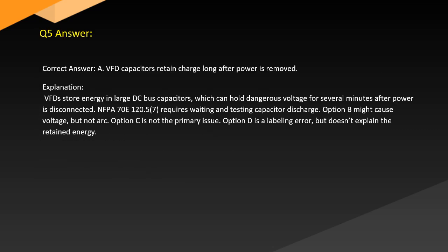Answer. Correct answer A. VFD capacitors retain charge long after power is removed. Explanation: VFDs store energy in large DC bus capacitors, which can hold dangerous voltage for several minutes after power is disconnected. NFPA 70E 120.5.7 requires waiting and testing capacitor discharge.